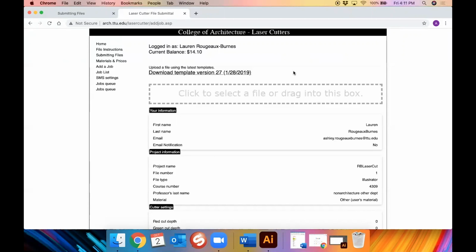And then the next step is to take your fabric to the architecture building. So I want you to use the fabric at the very beginning of the semester that you bought for laser cutting. So I suggested at the beginning of the semester that you buy a man-made fiber. Those typically laser cut better than natural fibers, because natural fibers will burn on the edges, but they do not singe, they don't sear, so they will still fray.